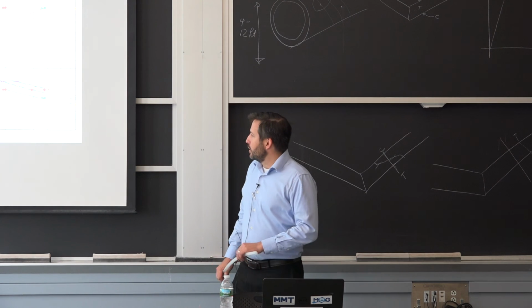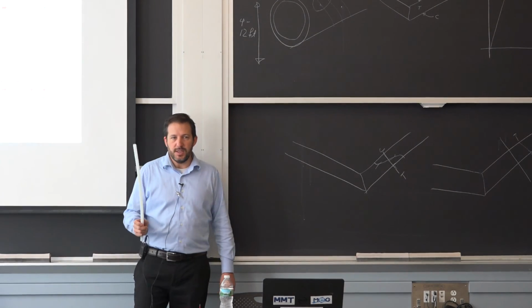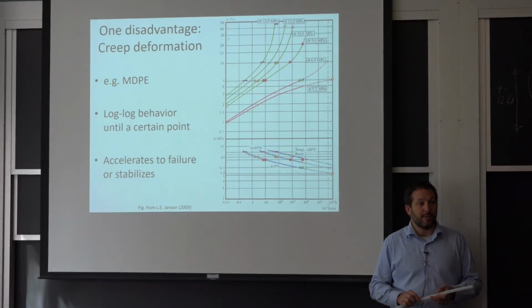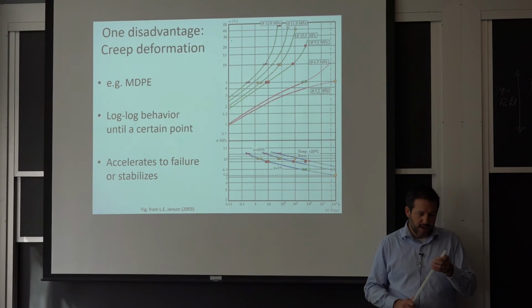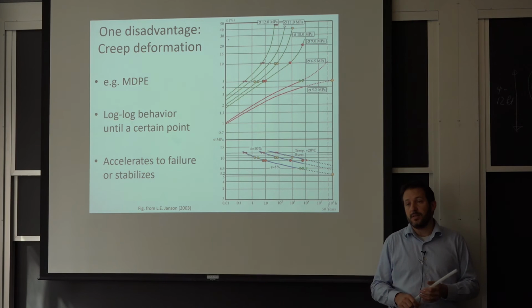So I have a lot of bullets here, but it reminds me to say that even though plastics won't corrode, they can degrade a lot. So this polyethylene piping needs to be filled with an antioxidant package.